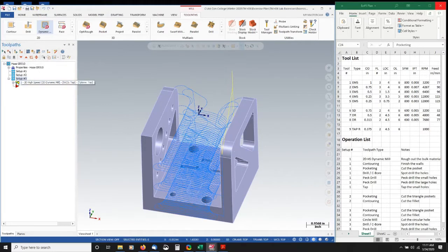I've currently created this particular toolpath in setup number 3. See that? So I need to drag that up and drop it into setup number 1. And then I'll make sure that my insertion arrow is now in setup number 1 for the rest of this particular programming job as it relates to setup number 1.